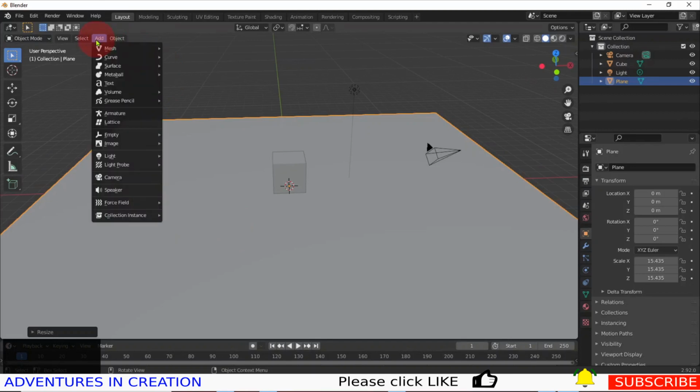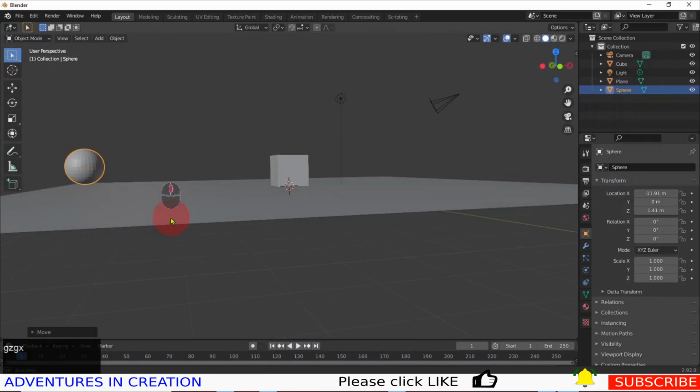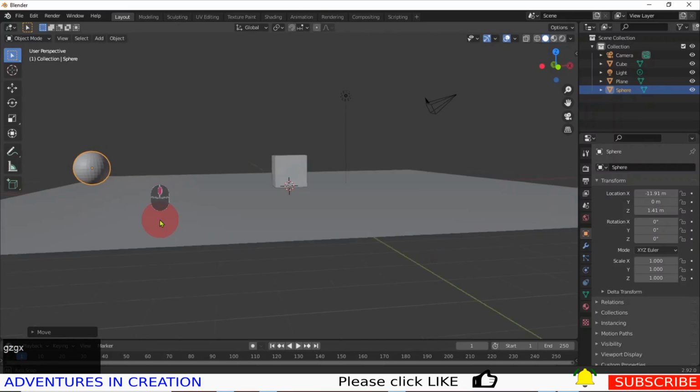And then we want to add a ball. So again, it's add mesh. And in this case, we're going to say a UV sphere. So we're just adding a ball. Everything adds in the middle there. So we're going to G and we're going to Z. We'll just move it up a bit. And we're going to G and X. I'm going to just move it to that side. Just put it there. And simply, that ball is floating in the air at the moment.